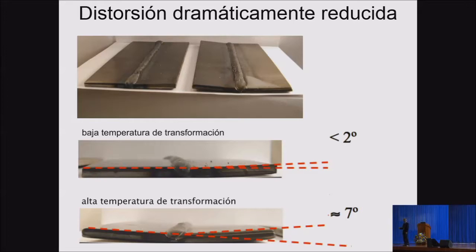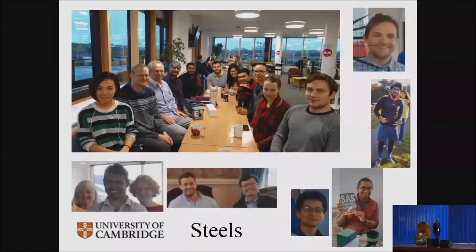We are now working on looking at overloads. That means that supposing you have a Caterpillar tractor, it's not going to just undergo a steady load. Sometimes it will hit a rock and you'll get a big spike in the load, and that can alter the residual stress system. So we're working with TWI to examine specifically the effect of overloads on residual stresses.